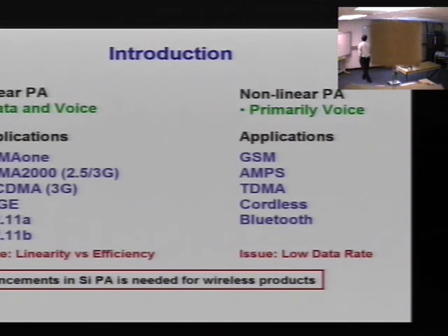And right now, the dominant products are in gallium arsenide to meet these requirements, primarily because the devices used for gallium arsenide, the HBTs, operate on a substrate which is semi-insulating, which can have very good efficiency. But nevertheless, there's been a lot of advancement in silicon device technology, and looking at silicon PAs, there's definitely potential, at least I would say, in the 2 gigahertz and below band.